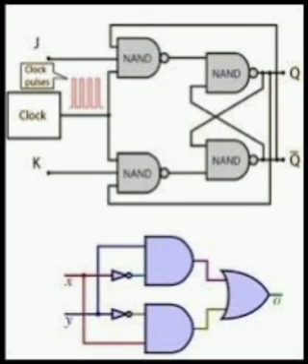Full subtractor is a circuit which performs subtraction between two bits, taking into account that one may have been borrowed by a lower significant stage. Logical expression: difference D equals A XOR B XOR C, borrow B naught equals A bar B plus A bar C plus BC, equal to A bar B plus (A XOR B) whole bar into C. A full subtractor can be implemented with two half subtractors and one OR gate. The number of NAND or NOR gates required to implement the full subtractor is equal to 9.